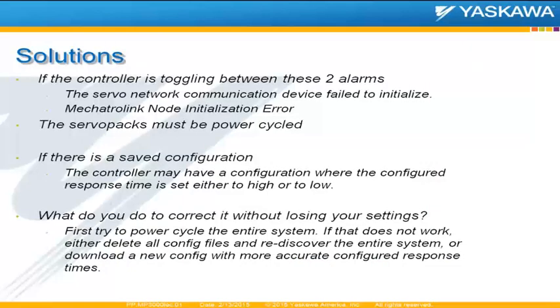So what are some of the solutions? When you see the controller toggling between these two alarms, the servo network communication device failed to initialize and MPiec node initialization error, the Servopacks must be power cycled. They won't show any alarm, they won't give you any indication there's anything wrong, but you'll never be able to connect with the controller until those Servopacks are power cycled.